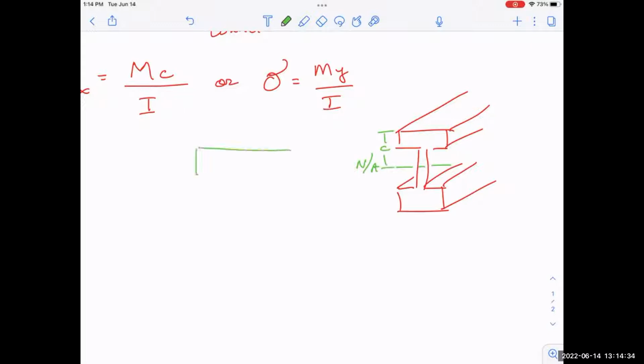But we're going to look at a problem sometime, maybe like this, where now all of a sudden the neutral axis is really hard to locate. You understand that? And this is not an uncommon shape. Does it make sense this shape would be a place where you were very worried about compression? Because there's a lot of material up there to keep it from compressing. And of course, that's going to keep it from bending. If there's not much material up there, then it's going to want to bend a lot. Maybe I don't want it to bend. Okay, that's a roadway. There's trucks driving across it, trains. And so, okay, let's put that up there on the top.